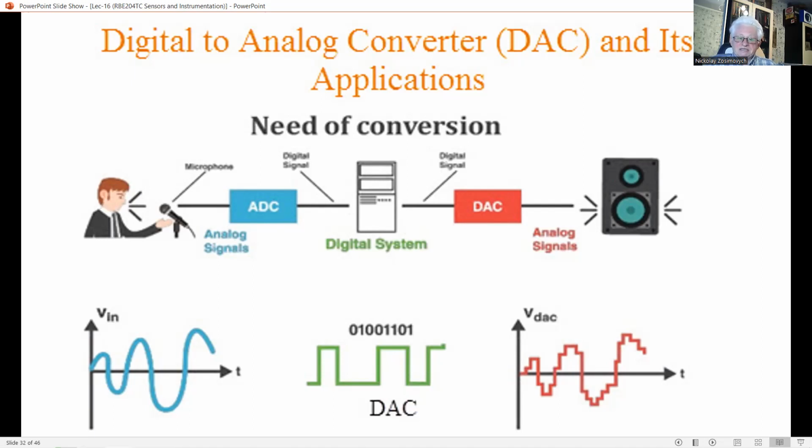A typical DAC unit is an active circuit in the form of an IC chip. It may consist of a data register, solid-state switching elements, resistors, and op-amps powered by an external power supply, which can provide the reference voltage for the DAC. The reference voltage will determine the maximum value of the DAC output.